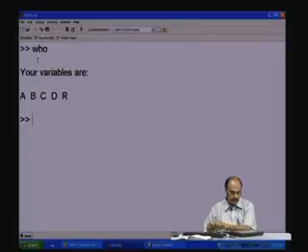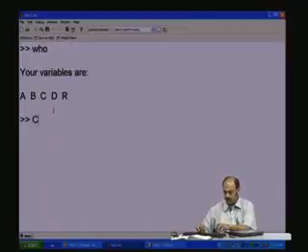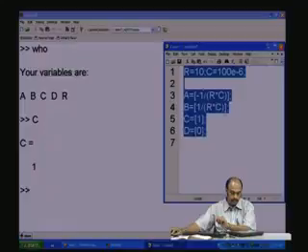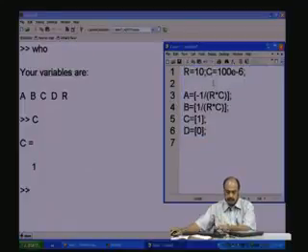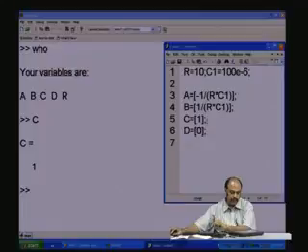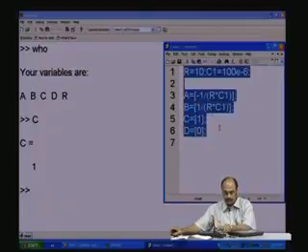There is one particular issue. There are two variables here, C. One is for the C matrix, one is capacitance. So, we cannot mix the variables, and therefore, I will go and change this as C1 instead of C, and we make this as C1, make this as C1, so that there is no confusion about the variables.